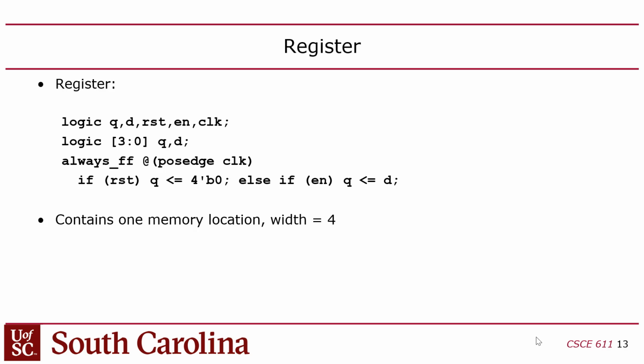Okay. Yes. Doesn't the value come from the immediate field in that instruction? No, the immediate field is... so the instruction is CSRRW, right? Yeah, I think that's right. And then you have a register, which is your RD, and then you have an immediate, which is 12 bits. This is 5 bits. And then you have an RS1.